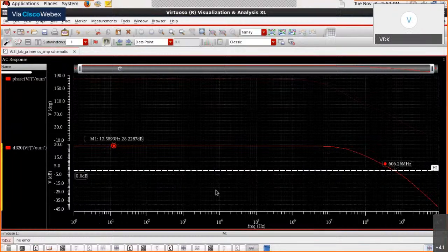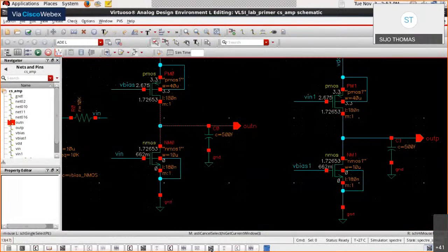Right, so what is more interesting is if I go back to the previous circuit or even this circuit, by reading off the capacitance values from the small signal parameter listing given out by the tool upon operating point analysis, can I do some quick hand calculations to figure out the locations of the poles and the zeros? Do we have that calculation table? Yes, sir. All right.